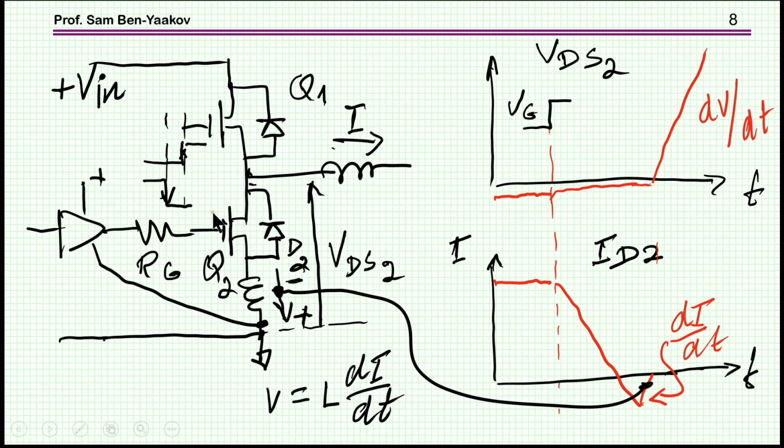And if this voltage is high enough, the transistor will start conducting, which is very bad because we are going to have a shoot through. So this is one problem we have. We have this induced voltage due to the diode and the inductance that we have here. And in this case, going back to the bipolar drive, if this is not zero here, but rather negative, then we can allow more negative voltage across this inductor before we have any problem. It is important to realize that the di/dt, which is of course important to the value of the voltage that you might get, the magnitude, could be of different kinds, and there are some diodes with soft recovery, so that this di/dt is slower, and consequently the voltages will be lower.